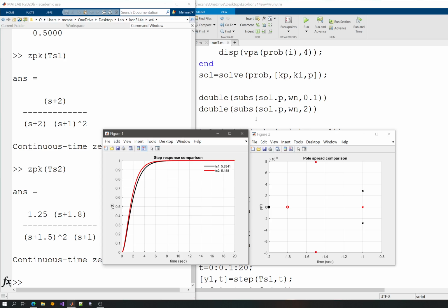There might be possibilities where we have a pole zero cancellation, but it is not always a good idea, since it is a hard restriction on one pole and one zero. So we can debate whether a pole zero cancellation is better, or a dominant pole placement that has a high dominance factor is better. That might depend on the system and setup. But most of the time, the Matlab code for PI, PID, PD, and even more controllers that can be derived from those can be designed with the same Matlab code with small modifications.